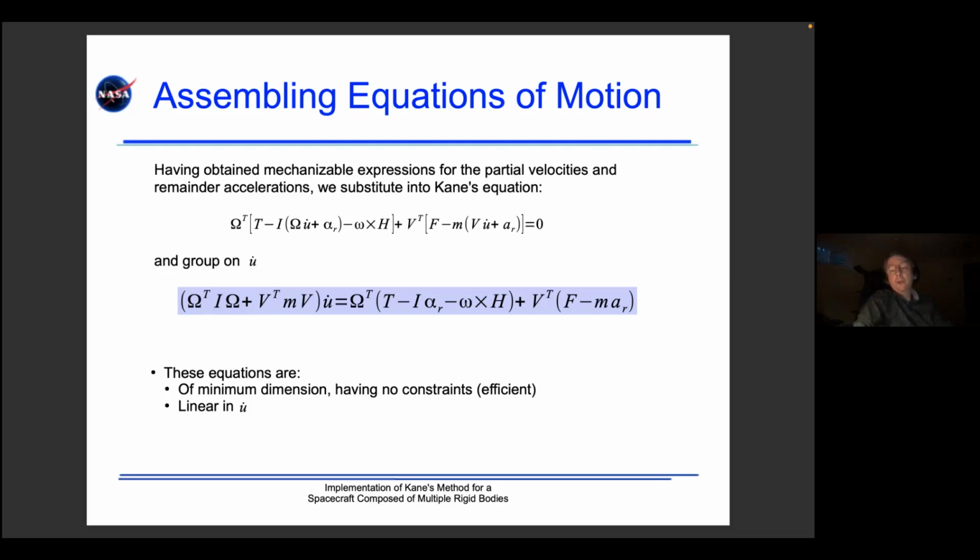You notice through this whole talk, I've talked about generalized speeds. I haven't even mentioned generalized coordinates. Right, I use them a couple of times, the thetas in the joints and so forth. Those are generalized coordinates, and Lagrange starts with those and then takes q dots and then another derivative with respect to time. But one of my favorite generalized speeds, angular velocity, there's no q where q dot equals omega.